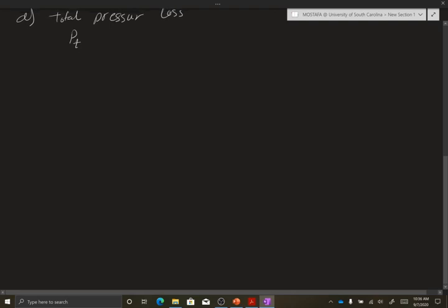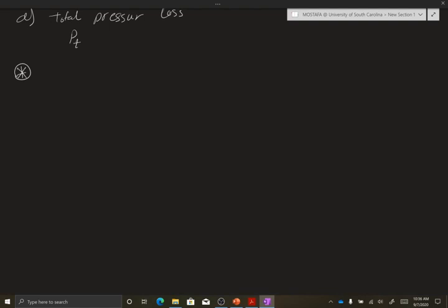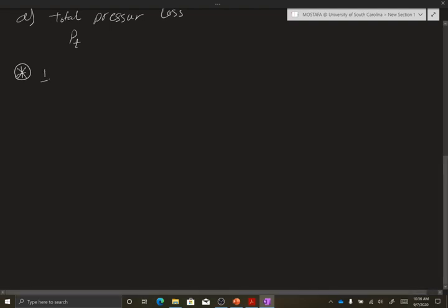As you can see, we have a constant area duct with heat transfer. So the first assumption you can make is that you are going to neglect the wall friction because you have heat transfer. It is constant area, so it resembles Rayleigh flow.